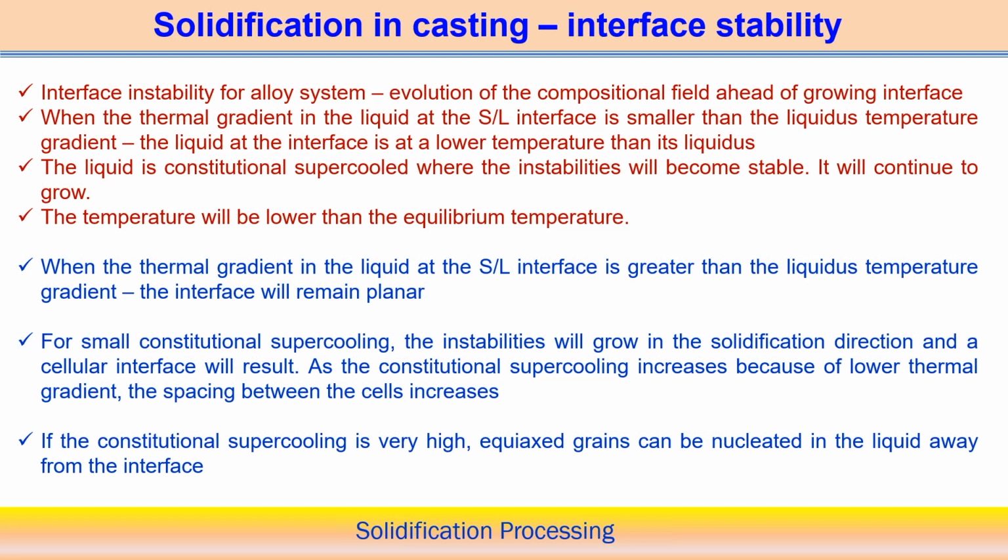Now if we look into interface stability in the case of an alloy system, it is actually governed by the compositional field, the changes of the compositional field, the concentration gradient in front of the growing interface. So what kind of compositional changes occur in front of the solid liquid interface actually influences the instability for an alloy system.